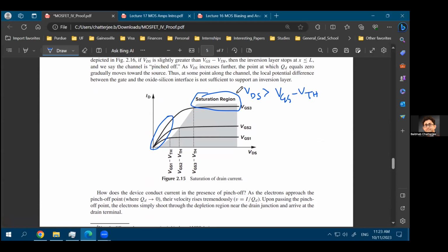and again, as I said earlier in the class, whenever we are talking about output impedance or input impedance, these are AC output impedance, AC input impedance. We're not talking about DC potentials or DC resistances here. It's all AC. Unless you're talking about biasing, we'll come to biasing in the next lecture. But unless you're talking about biasing, it's all AC. So if you're applying an AC voltage at the output, that means the output voltage is changing by a little bit amount.